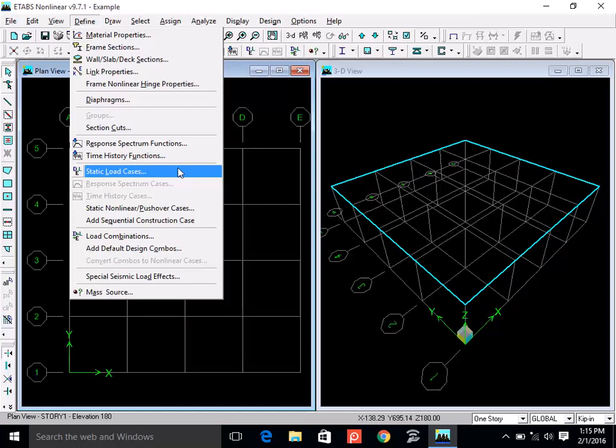In the new version, load cases is an additional feature. You may have defined several loads: live load, dead load, earthquake, wind, and all that. If you want to run the analysis for only one load pattern, for example, just earthquake, although you have defined all in patterns, you can go to cases and switch on or switch off the loads for which you want to analyze the structure.